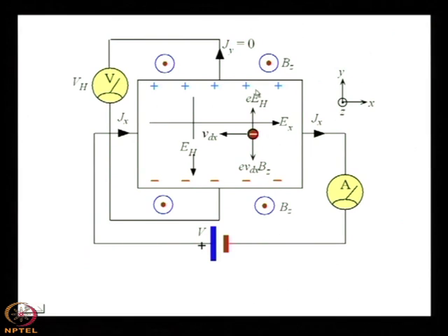It is because of the magnetic field, the Lorentz force, that they will push the positive particles upward and the negative particles downward. So, you can consider that there will be a dipole type of arrangement. Under such a circumstance, an electric field will be generated, and that is why this E H will be generated, which is the Hall field. It is because of the Lorentz force.